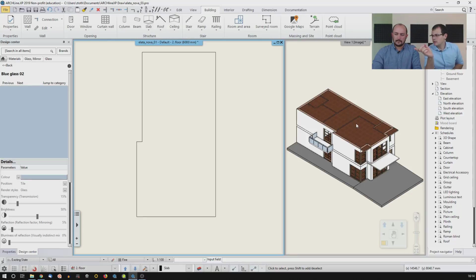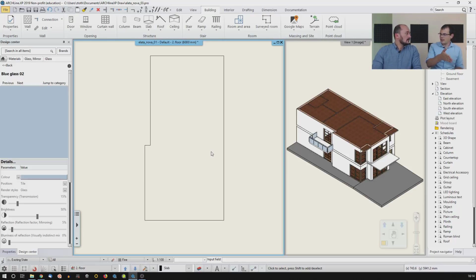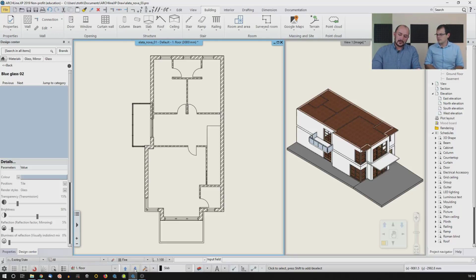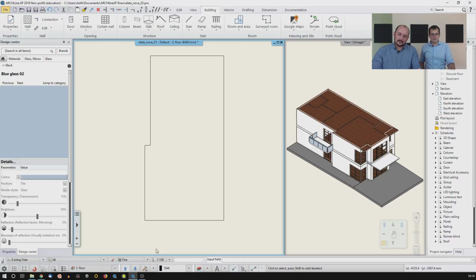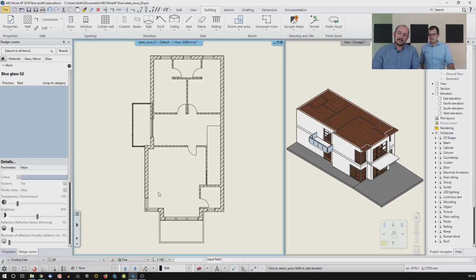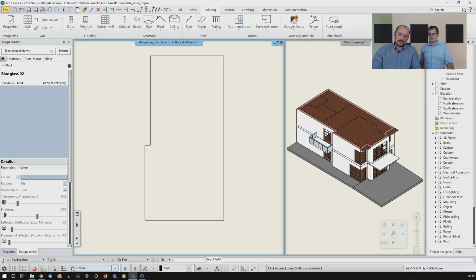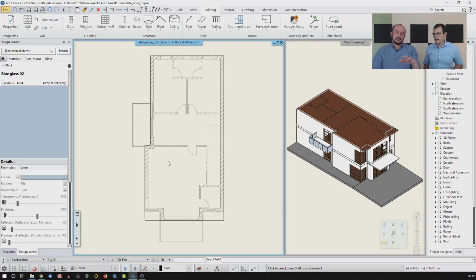One thing comes to mind. We are going to have a firewall on this building, which means that we might need to offset this slab, the ceiling, back a little bit, so that way we can draw that. But how do we offset it without seeing how far we have to offset it? Yeah, well, what you talk about is clearly visible when we jump there and back to see there's actually a thickness of the wall. And if I would like to make this floor visible on this floor, I can use this jump list here. This tiny arrow brings up a jump list of the existing floors, and if I click on the little bulb here next to the name of the first floor, and then I click into the drawing, it makes the other floor visible.